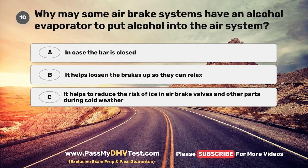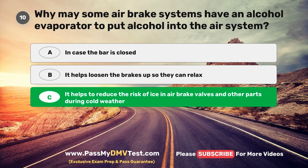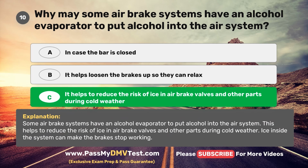Question 10. Why may some air brake systems have an alcohol evaporator to put alcohol into the air system? A. In case the bar is closed. B. It helps loosen the brakes up so they can relax. C. It helps to reduce the risk of ice in air brake valves and other parts during cold weather. The correct answer is C. It helps to reduce the risk of ice in air brake valves and other parts during cold weather. Some air brake systems have an alcohol evaporator to put alcohol into the air system. This helps to reduce the risk of ice in air brake valves and other parts during cold weather. Ice inside the system can make the brakes stop working.